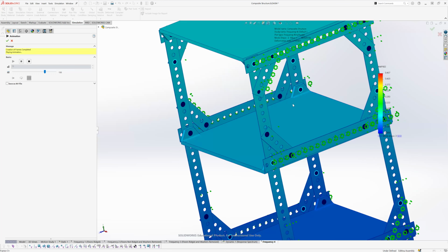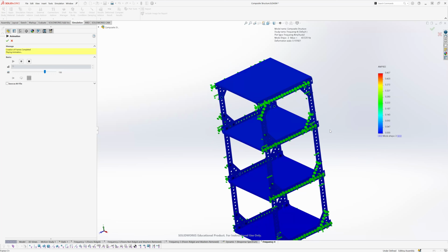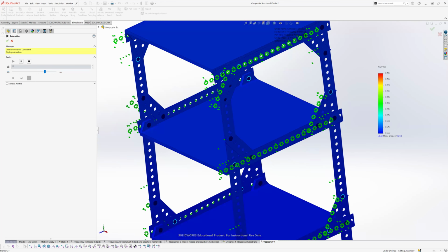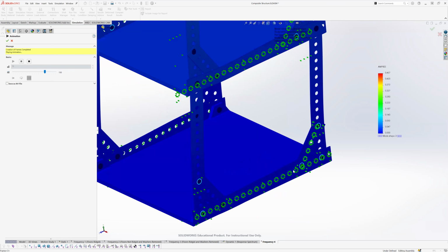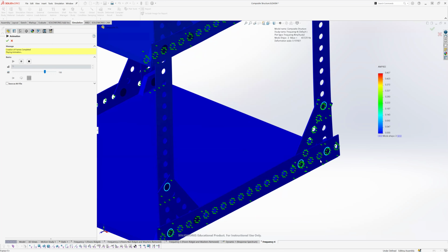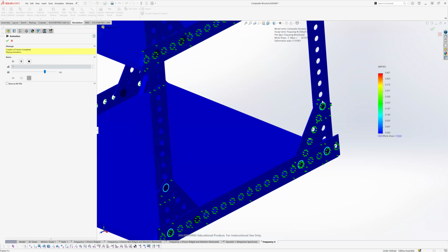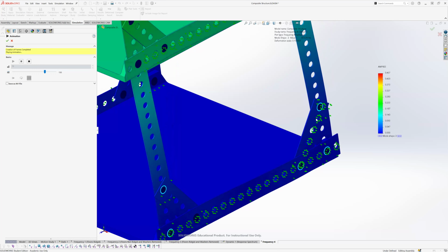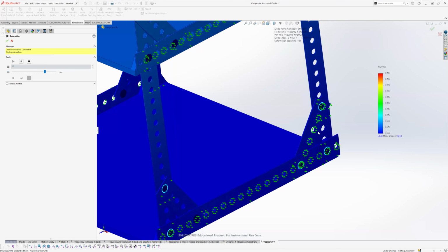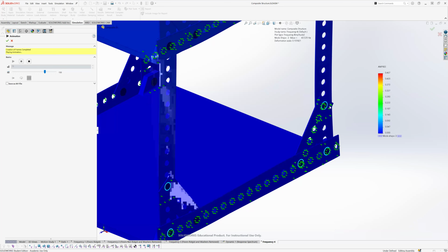Again, check these pins. Those look good. If these weren't acting correctly, what you end up seeing is a member, like I'll try to go down here, because that sway back and forth is going to give me a headache. Another thing you can look at is if this one wasn't constrained properly, you might see this member still moving back and forth, but this member here just staying where it was, or it might be moving, but not in sync with that pin.